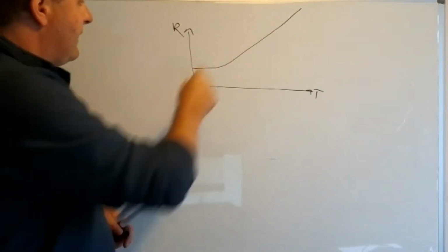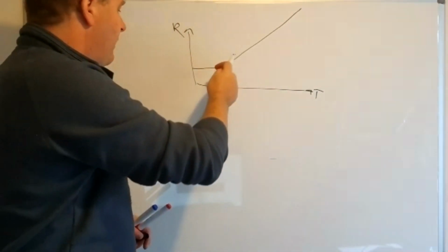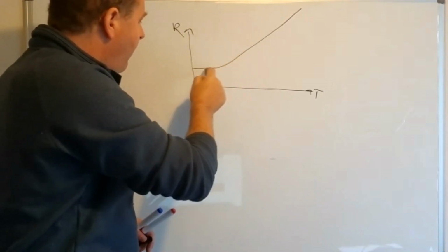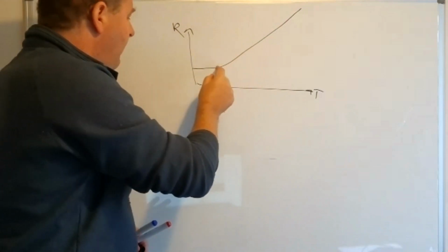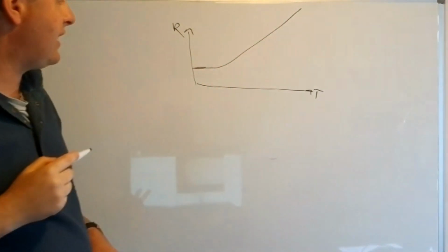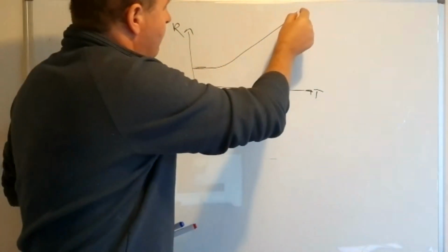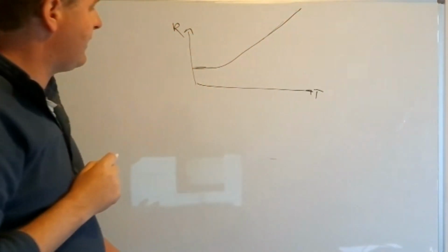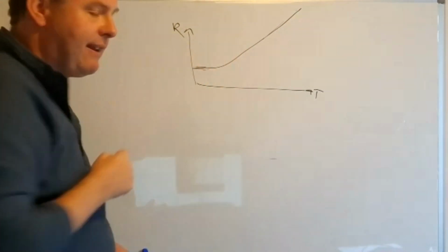So it's linear, or near enough linear, over quite a broad temperature range. Then there's a region here where it goes as temperature to the fifth, and there's a classic physics question about why it's to the fifth, and then it levels off at some residual resistivity. So if you want to use this as a temperature sensor, then in this regime here, you have a nice linear dependence between the temperature and the resistance. Of course, it falls off and stops working as you get cold because the resistance levels off.